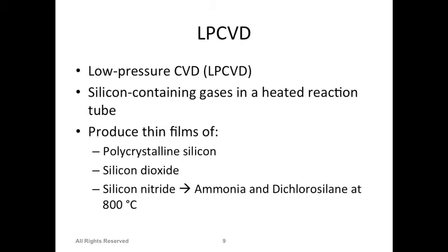So if you have aluminum, which is a very common material previously used to make electrodes on the surface and still utilized in solar cells and all that, it has a melting temperature of 660 degrees centigrade, and you are performing another process to deposit silicon nitride on the surface at 800 degrees centigrade. It will not work, because at 800 your aluminum will be melted, right? So how can you deposit material on the melted surface? If you have made electrodes, they will be spread all over the surface. But it gives you a very nice silicon nitride at least.